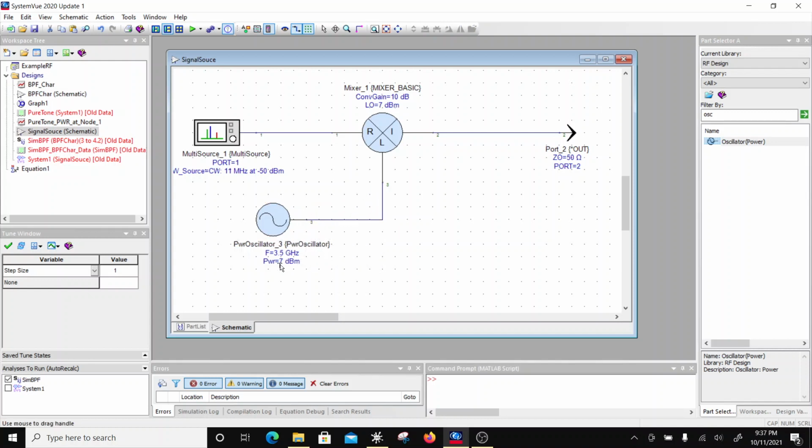Now here there is a good isolation between RF and LO because these two frequencies are very far apart, right? So that's not an issue. In down conversion, you will put here what you call an injection filter, right? Because you have to improve the RF LO isolation. So that's what's going to happen.